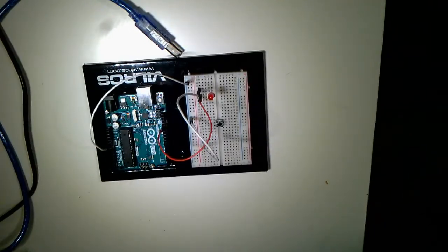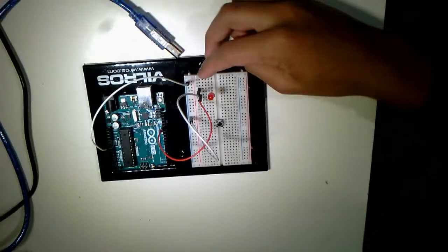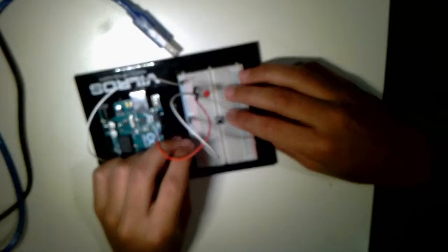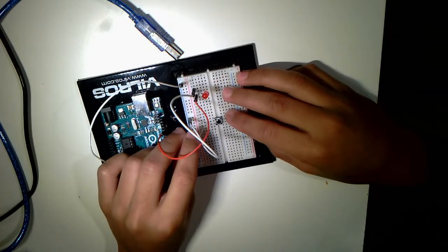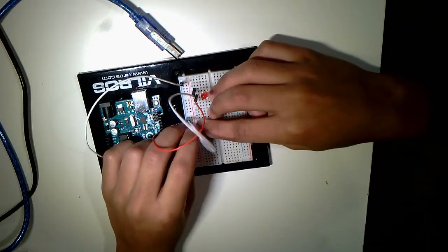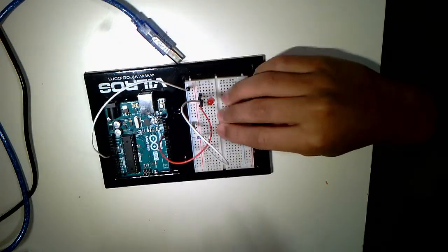So the next step is to connect our button to ground. Now you'll recall that we already have our ground rail that has ground in it, so we can use that same rail for the button. And since we're just plugging a resistor in for the ground, we don't really need a wire. We can just plug our resistor in directly. So we'll plug our resistor to the ground rail, and we'll plug the other end of the resistor to one side of the button. I'm plugging it to the left side.